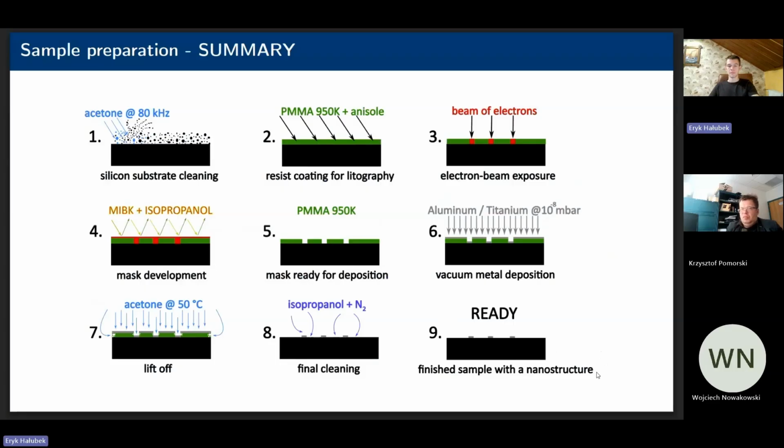Before making all these steps, you can think of the specific needs that are required for the material that you want to evaporate because, as I said, titanium, for example, is really problematic right now, especially as I'm doing these samples, where the aluminum was much easier to handle because titanium has much higher reactivity than aluminum and a higher melting point.